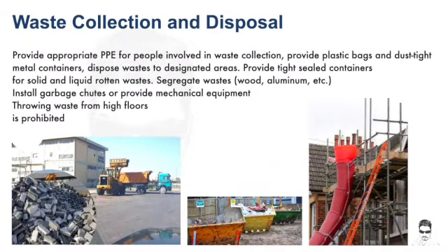Provide appropriate PPE for people involved in waste collection. Provide plastic bags and dust-tight metal containers. Dispose waste to designated areas. Provide tight sealed containers for solid and liquid rotten waste. Segregate waste. Install garbage chutes or provide mechanical equipment. Throwing waste from high floors is prohibited.